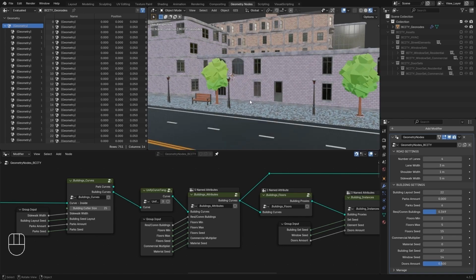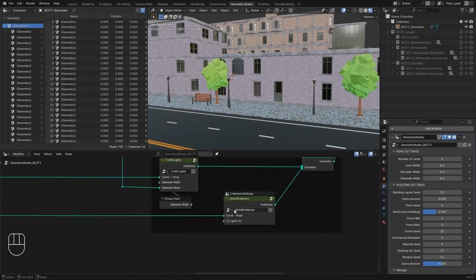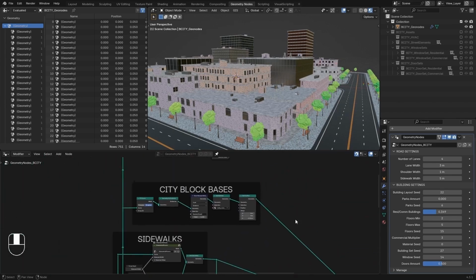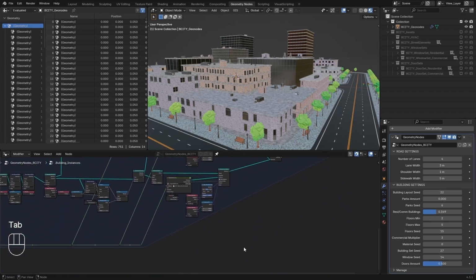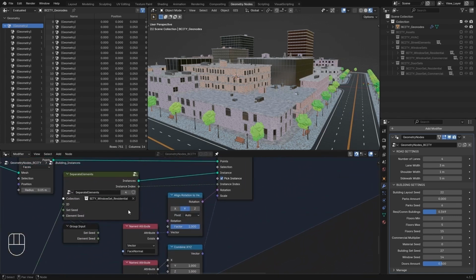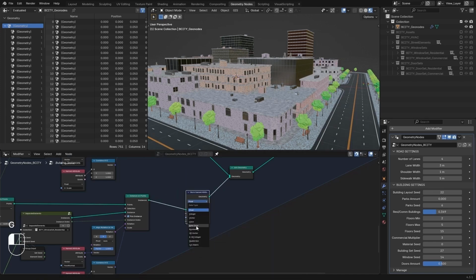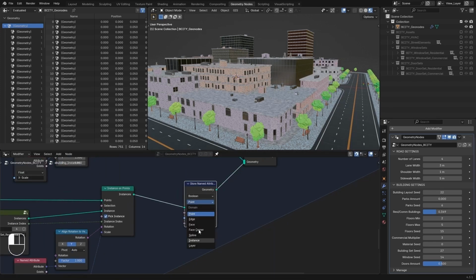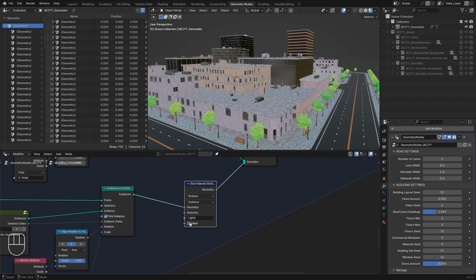Earlier in the course, when we created our streetlights, we used a Boolean toggle to switch the lights on or off. We want to reuse that same Boolean to control whether the window lights in our buildings are turned on. So we go back into our building instance node group, and locate the part where we assign the windows. Right after instancing, we add a store named attribute node. Set its type to Boolean and assign it to the instance domain. We will call this attribute lights.